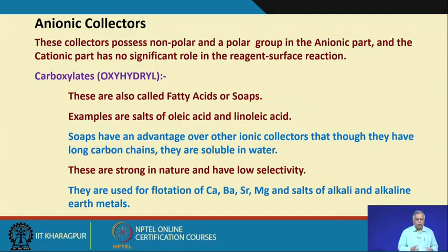So, what is the issue here? Your collector must first be dissolved into your solution, and then the cations and anions are released. The anionic part in this type of anionic collector has a polar and a non-polar part, while the cationic part does not have a significant role to play.